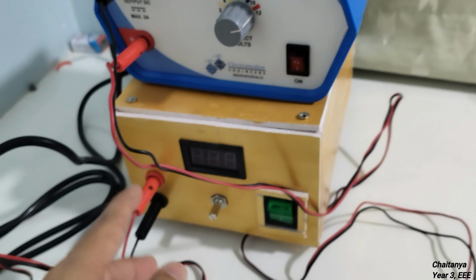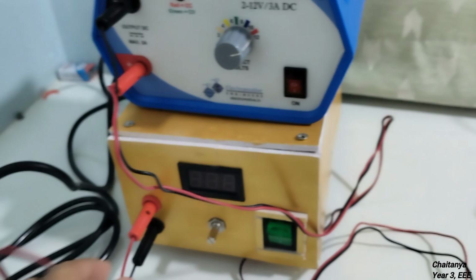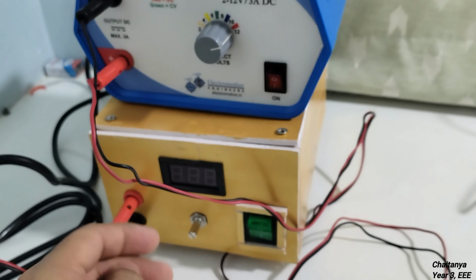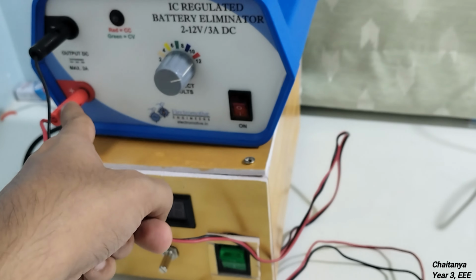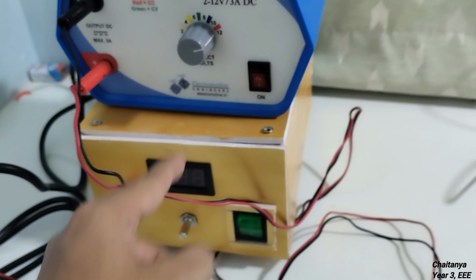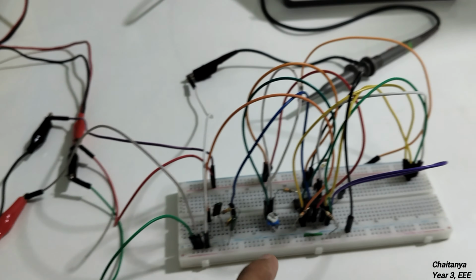So these are the DC outputs, as we know, they're DC supplies. If you tie the negative of this to the positive of this, basically you're going to have a common ground. If you check that common ground with respect to this, you're going to have plus VCC, and with respect to this negative, you're going to have a minus VCC. So that's how you can set up a dual supply here and give it to the op amp.